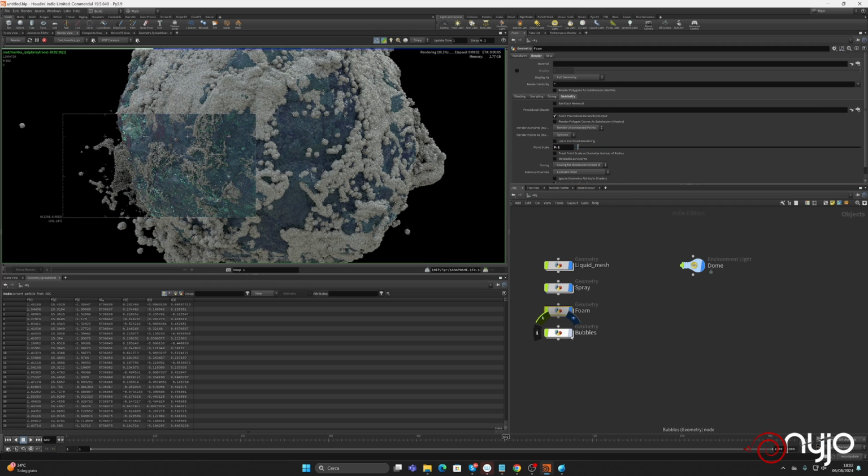And about the bubbles, for the moment it's not a problem, it is inside, so you have not to take care about it. Let's remove the sprite just for a moment. Maybe we can go a little bit lower with the foam. Let's try with 0.05. And then we have again the spray. Okay, what about the material?